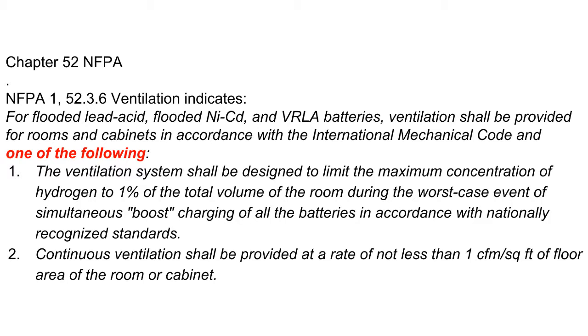So you can get away with a very small dedicated air handling unit just for the batteries if they are in a dedicated cabinet with little caps that go over the tops of the cells to capture the gas. You put a little vent hood, almost like a kitchen vent hood, over the batteries. They produce most of their gas when they're undergoing heavy charge cycles. So you can run this ventilation continuously, and you may ramp it up during periods of charging or discharging.